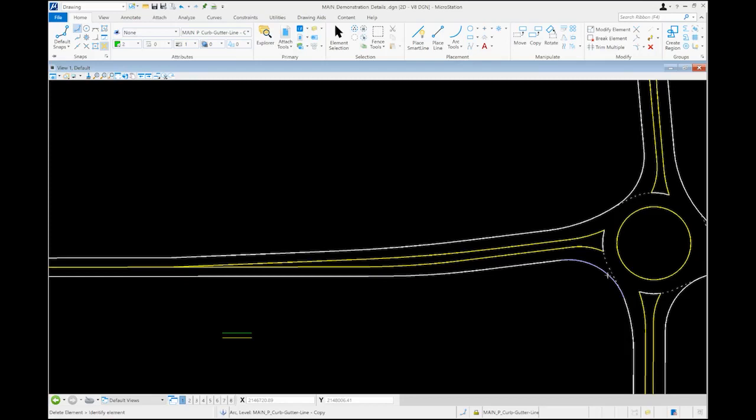However, slightly longer or shorter could be possible depending upon practical design considerations. Considerations such as driveway placement, approach visibility, and channelization all factor into that final splitter island length. But for starting purposes, we're going to use that desired 200-foot splitter island length and lay that in as a point of reference.